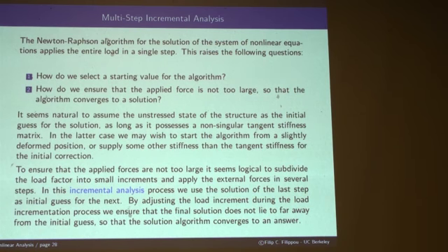That's the biggest scare of people with nonlinear methods, right? How much of a load can I put on the structure? Will it collapse with this load, right? And so, to avoid this problem, what you do is, first of all, you always run a linear analysis first.